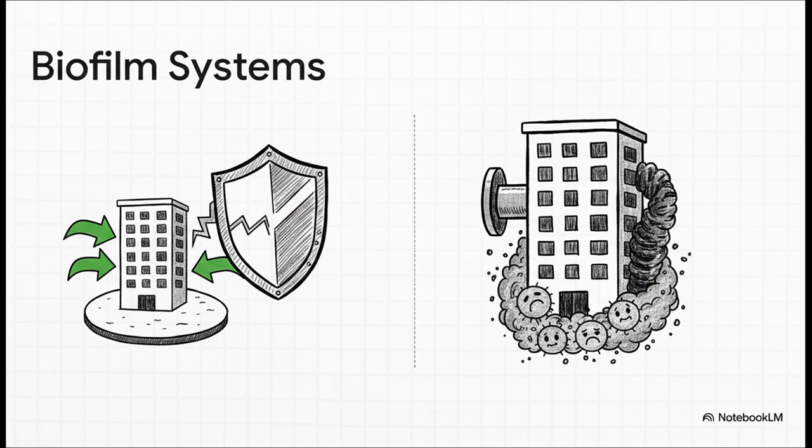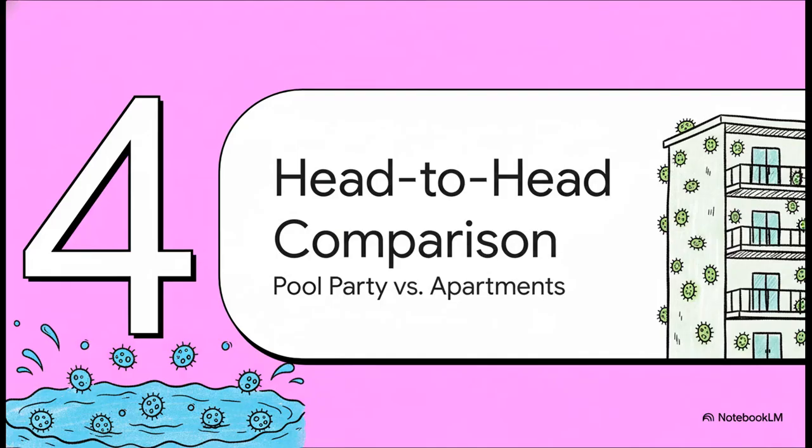So, the huge advantage of giving your microbes a fixed home is resilience. These systems have a much smaller footprint, they're way more resistant to sudden shocks, and you don't have to worry nearly as much about getting that sludge to settle. The main trade-off? Well, they can sometimes get clogged up, or maybe be a little less efficient if the wastewater is just extremely polluted.